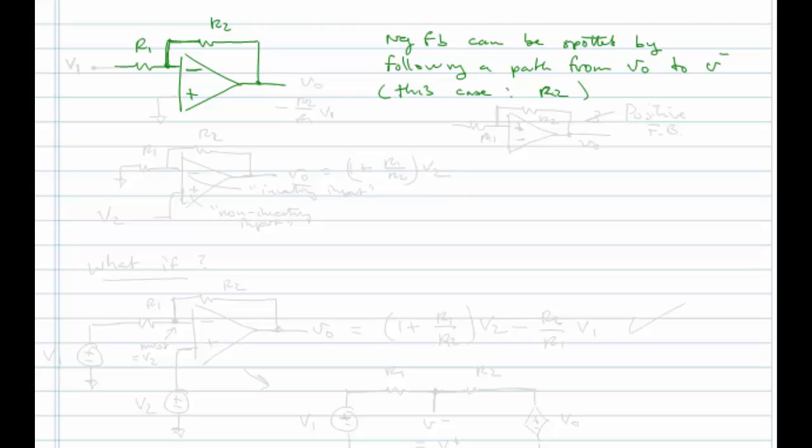All right, if I had something like this, okay, this is positive feedback. Why? Because the output VO is being fed back, but not to the negative input. It's being fed back to the positive input, and so that actually produces positive feedback, which has a very different result. So we're kind of in this sandbox now, in this discipline of negative feedback.